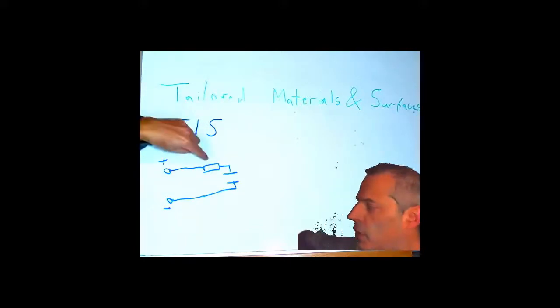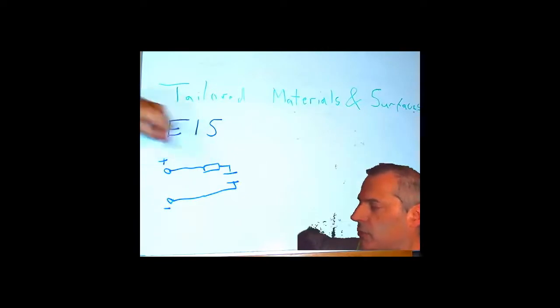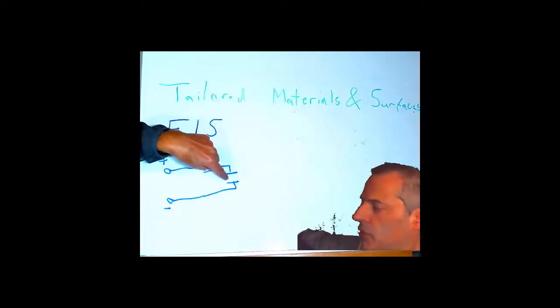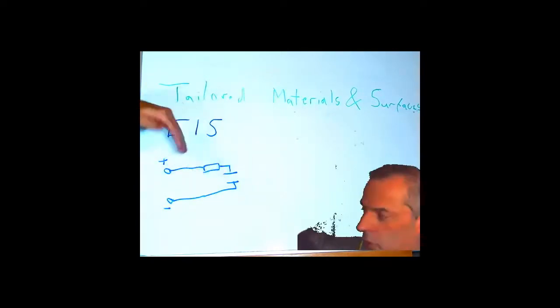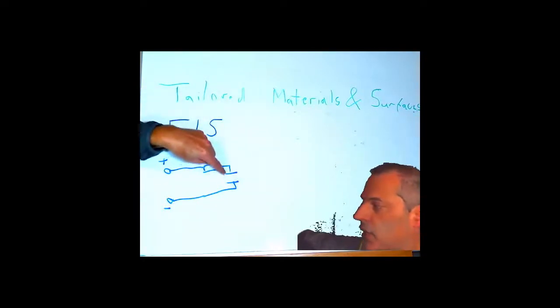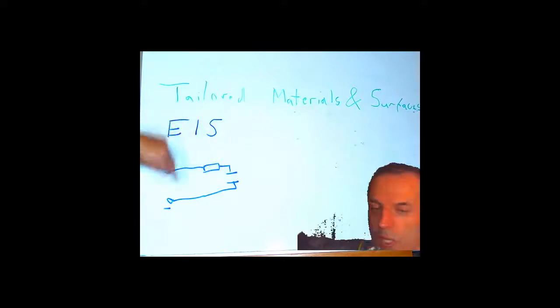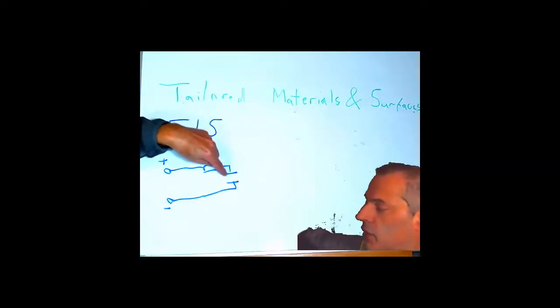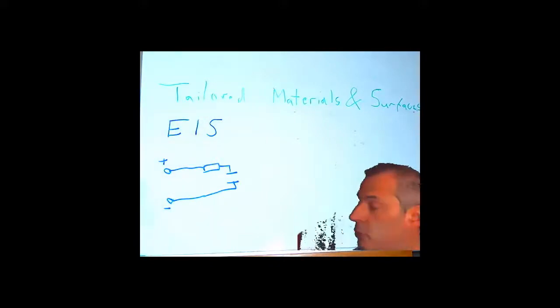So we measure this resistance at infinity, or at high frequency, and we measure the capacitor as a break in our circuit at very low frequency, and depending on how we connect our devices up, so we could put the resistor in parallel instead, and that would change how it charges up. So if we use our electrochemical impedance spectrometer to measure an electrical circuit, we can deduce a lot about it, what the components are.